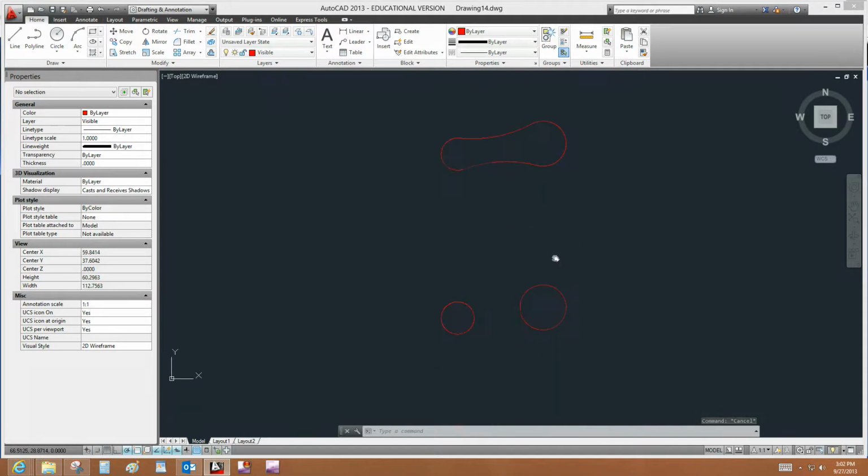So now I'm going to show you how to create this object in AutoCAD, and it's very simple. So what I want to do is just enter the line command, so L, enter, and tangent is something that is easier done with a one-time override in AutoCAD. So I'm just going to type in TAN, enter. So I'll click on this circle, and now I want to do it again, TAN, enter, and now it creates the tangent line. And I'll do the same thing for the bottom, so L, enter, TAN, enter, and it doesn't matter which direction I go. I can start here and go from right to left if I want, TAN, enter.